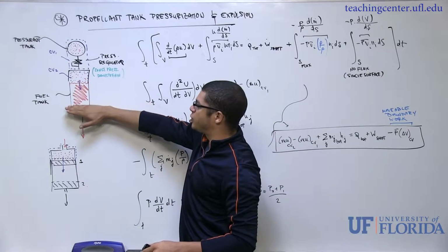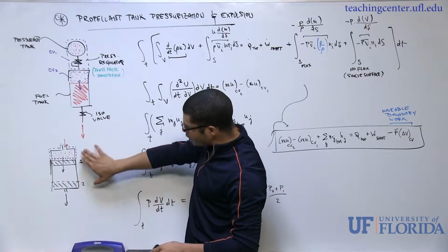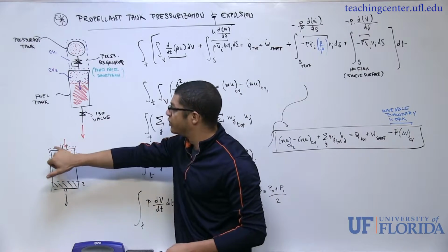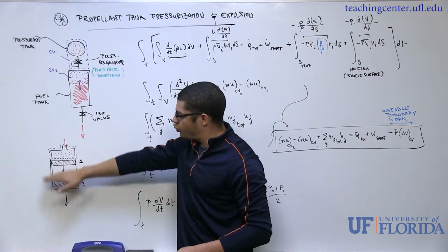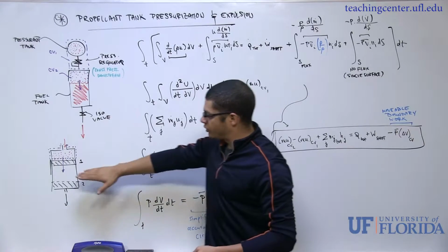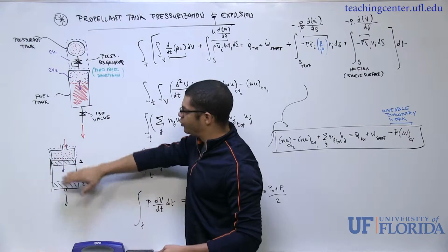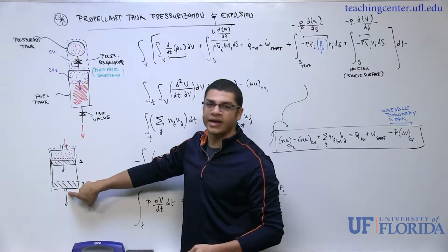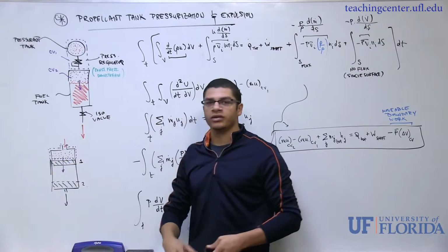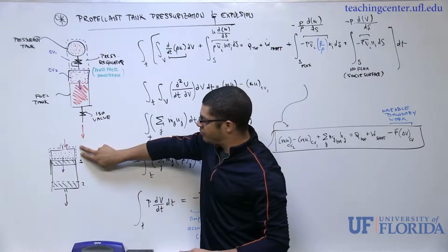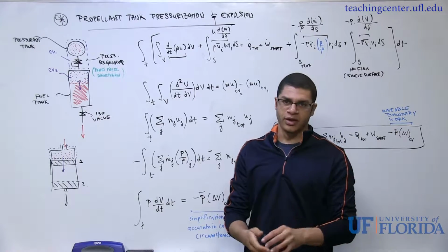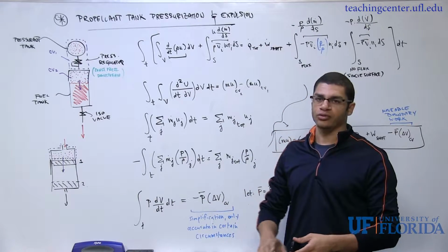And the only constraint is going to be once we reach the bottom of the tank down here. So that's very similar to a piston cylinder type problem where we have some kind of inflow at the top of the tank, and then the liquid we can just model as a piston, which may have some resistance or something that we can model like that. So we would be going from state 1 to state 2 in a piston cylinder assembly, and there could be an outlet fluid that's setting the resistance downstream, and we're ultimately interested in what happens to the fluid that's contained within our deformable control volume during this expulsion process.